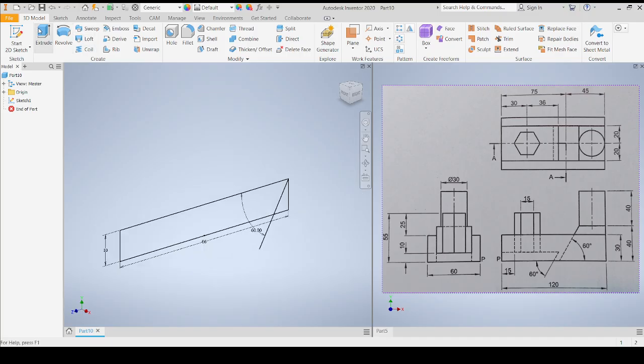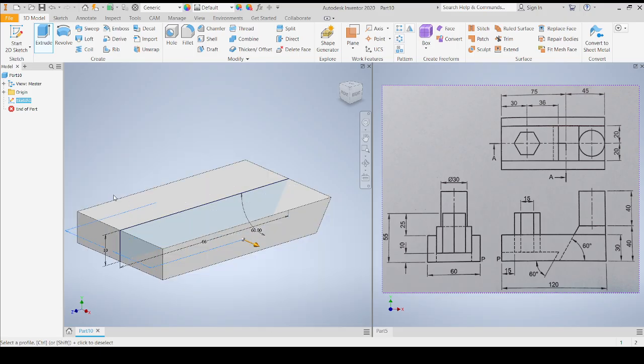And then you're going to extrude. Now, I want you to make a symmetric extrusion, meaning that both sides are equal, okay? Now, let's see. The length of this base right over here, from that point to that other point, is 20, and then from A to the other one is 20, meaning that the total length is 40, okay?